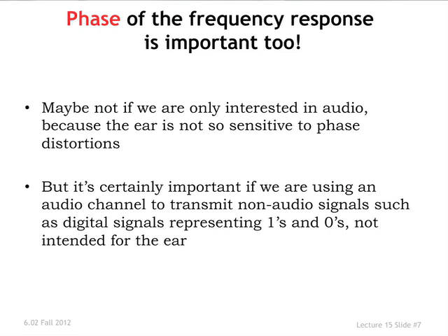Now, you haven't explicitly probed the frequency characteristic of the speaker you're using. You could do that, but instead you've been looking at things like step responses in the time domain and constructing eye diagrams. But you could look in the frequency domain and characterize your particular channel for your laptop sitting in a particular place. You could look to see what the magnitude and phase are like. Okay, so I want to go through this exercise of looking at the spectral content of a signal you want to get across this audio channel, and then looking at how the audio channel shapes it, and then what you pick up at the other end.